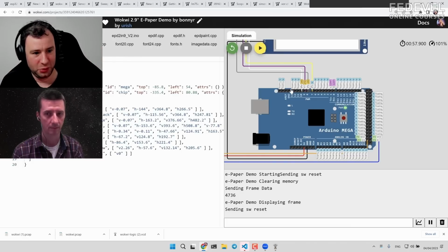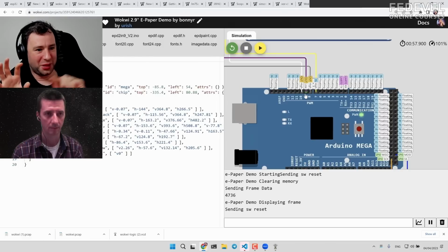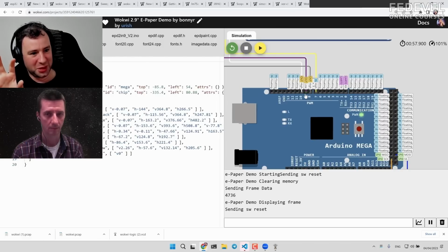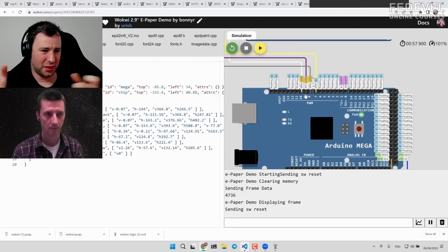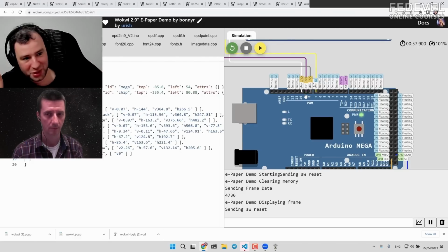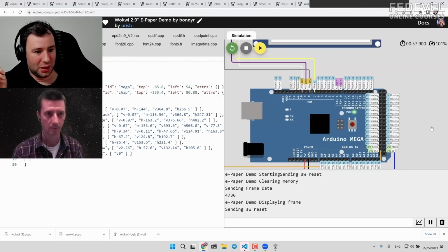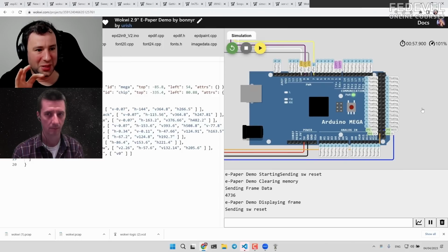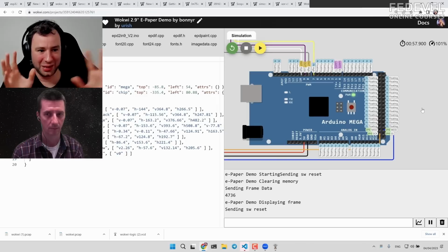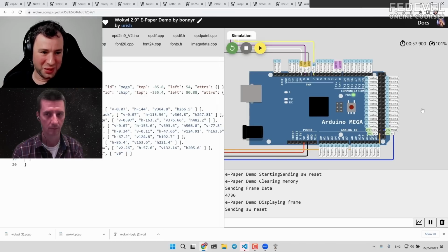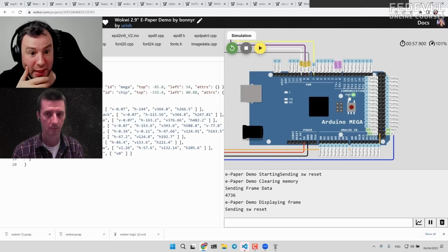Up until we added this, I had to connect the logic analyzer to the pins to see if there is any signal going on them, try to understand if it's the right signal, and then look for the right pins. I added this because I wasted so much time on issues where people said this is not working, and then when I checked, I figured out that the connections didn't match what the code said. So that's why I added this feature.